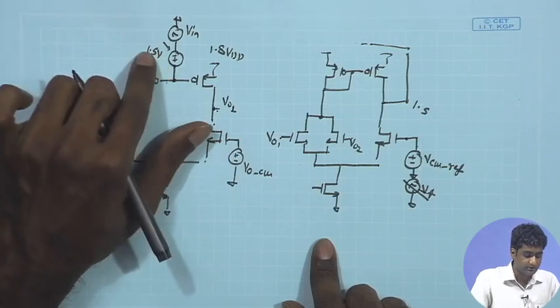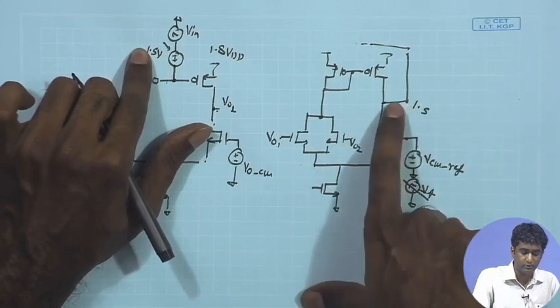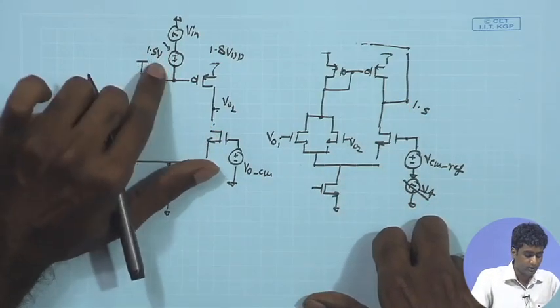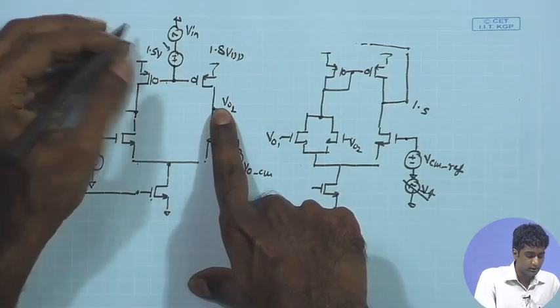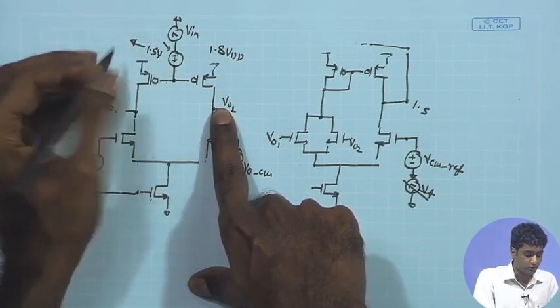Also, if you look at the DC value, you have to put very precise values over here, which are the same as the value provided by the feedback circuit, and if you are not getting exactly the same DC potential over here, it is also advisable to sweep this 1.5 volt DC across the mean value.